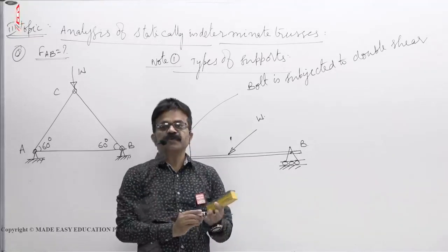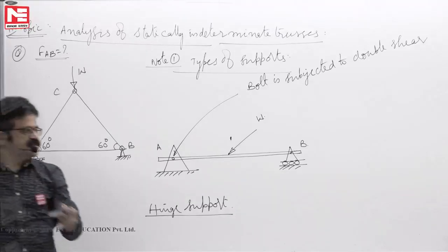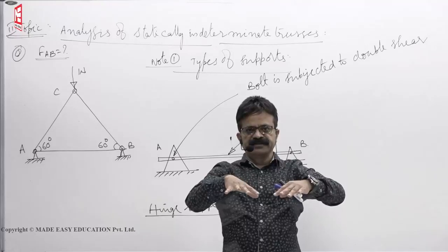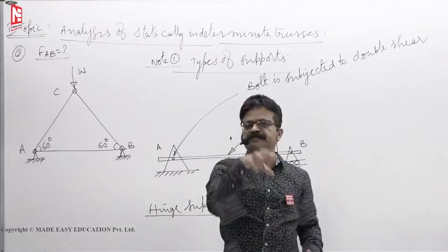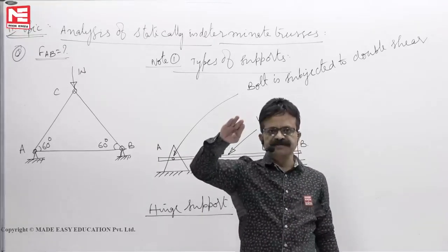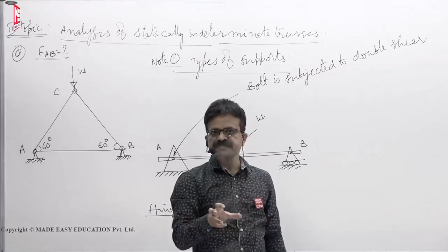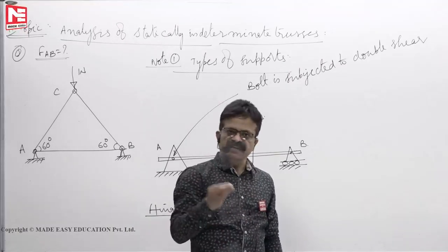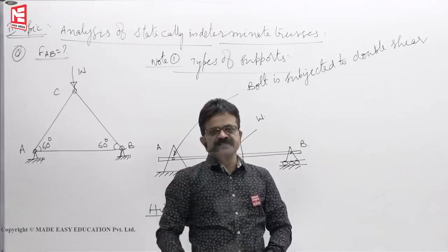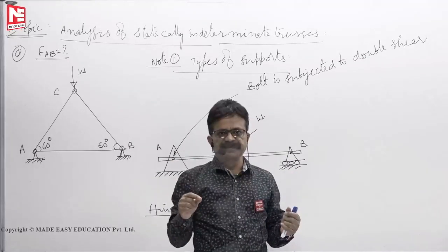That is because of the load dispersion. We have learnt, I think soil mechanics sir might have told you, that plate load testing when you are doing, when you load the plate, if the plate is resting on the soil, the pressure variation is like a pressure bulb. That is interparticulate system. Soil is interparticulate system. It neither behaves like a solid or liquid or the gas. So in such cases it varies like a pressure bulb.